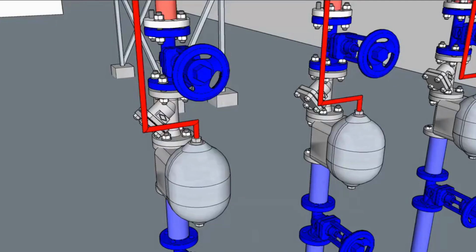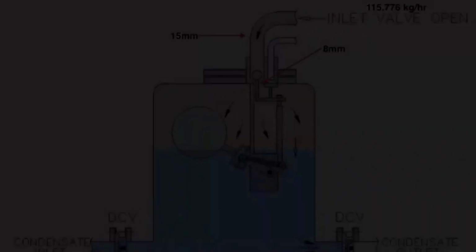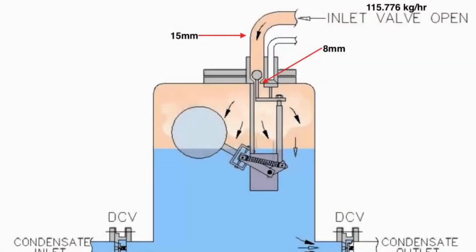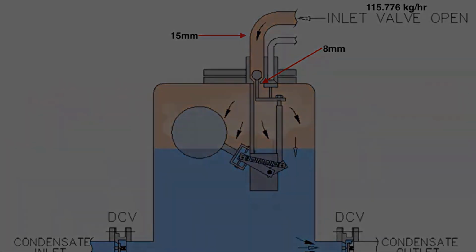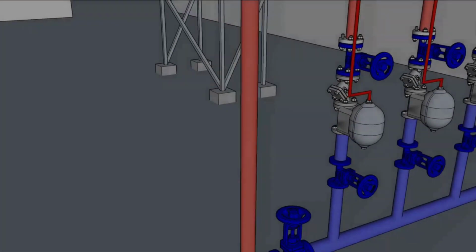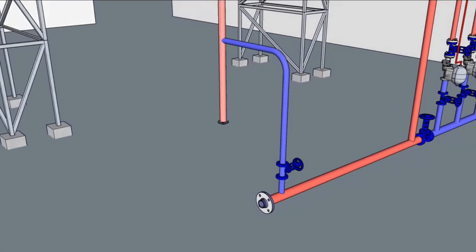All of the condensate generated was fed to a large collection header, which was serviced by a number of pump traps. This technology is based on motive steam driving the collected condensate back to the boiler house. The large pump traps would fill, and at a certain level, steam would be introduced to drive the condensate to its destination. The issue here was that steam was always engaged, which led to the majority of it being vented to the atmosphere.